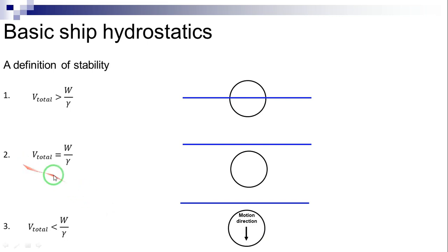In the above analysis, we assume that the specific gravity of the liquid, gamma, is constant throughout the liquid volume. This assumption may not be correct if large variations in temperature or salinity are present, or if the liquid volume consists of layers of different liquids. Interesting situations can arise in such cases. Other situations can arise at large depths at which the water density increases while the volume of the floating body shrinks because of the compressibility of its structure.